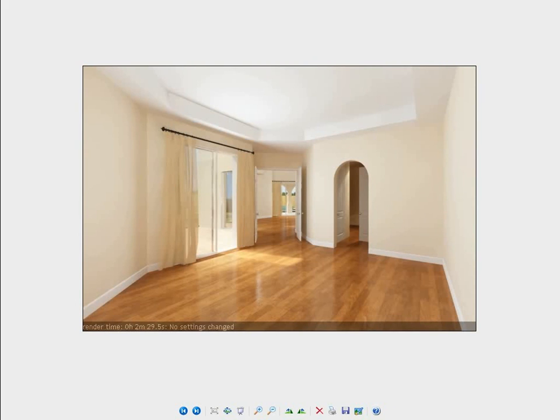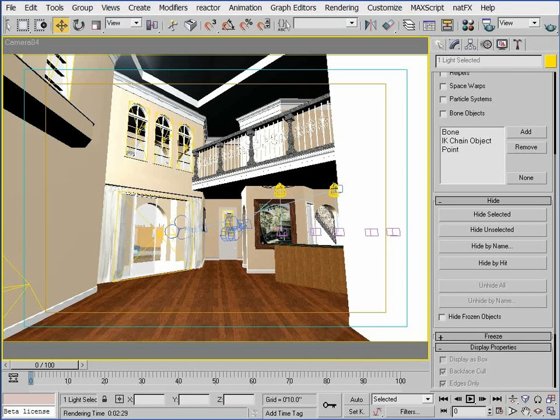I want to find my production render settings before I merge the furniture, because I don't want to render with all these extra polygons in my scene. It's just going to make doing test renders take forever. I'll start with the living room and do all my testing here. Chances are whatever works for this room is also going to work fine for the other two rooms. Unlike Module 9, where I demonstrated several different production settings and all the things that you should consider, I'm going to jump straight to my typical production settings for the irradiance map and the light cache, and maybe adjust one or two things that might have a significant impact on time and quality.